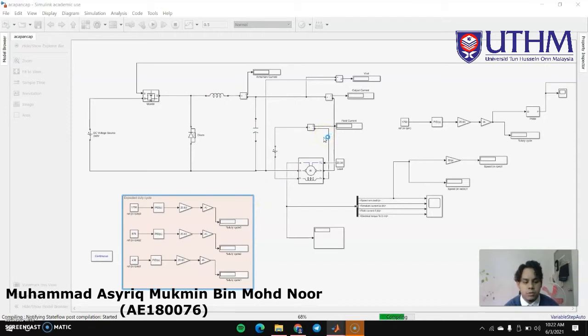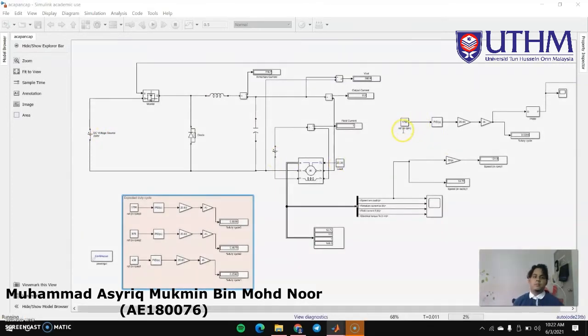Theoretically, the voltage output will be lower than 270, but for 1750 RPM, actually it will be the same, since 1750 RPM is actually equal to a duty cycle of 1, right? So the output will be 140, right? As you can see here, 140, and the duty cycle here is 1.